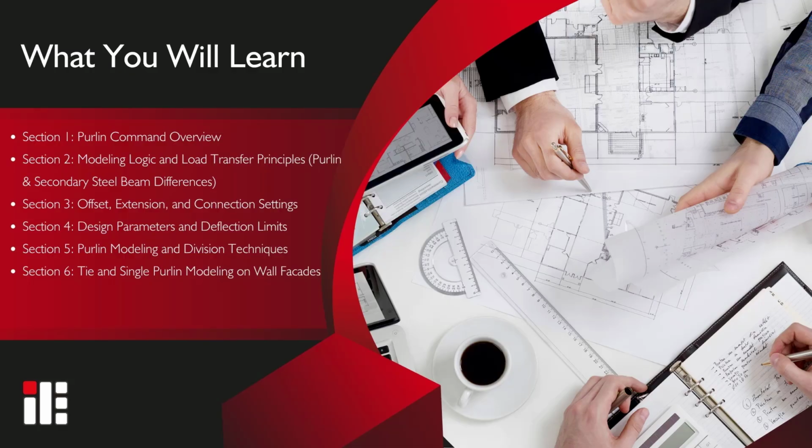This tutorial introduces the Purlin command in ideCAD Structural. It covers the logic behind Purlin modeling, including how purlins differ from secondary beams in load transfer. Offset, extension, and connection settings are explained in detail, along with design parameters and deflection limits. The workflow includes manual and automatic purlin placement, division techniques, and tie purlin modeling on wall facades. By the end, you'll be able to model efficient, code-compliant roof and wall framing systems using purlins.